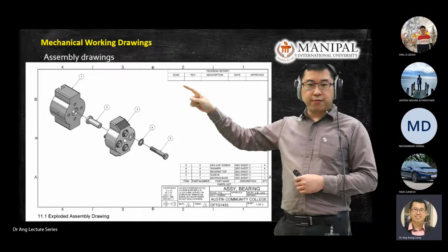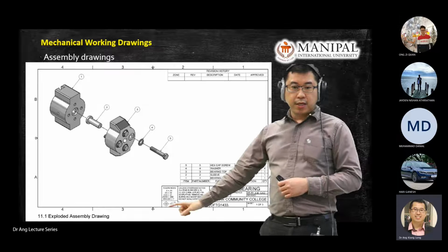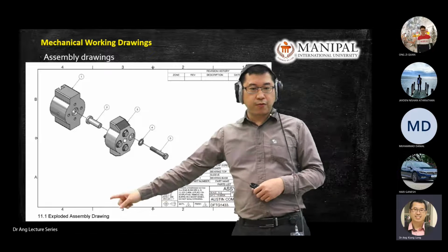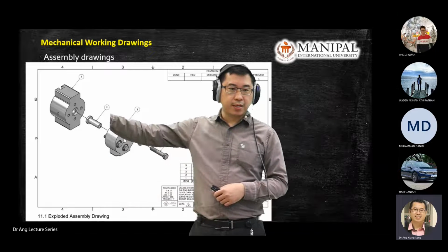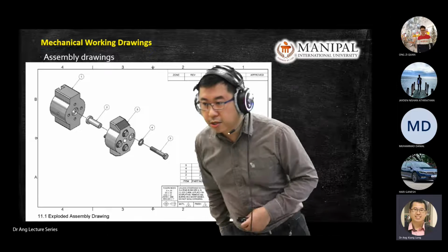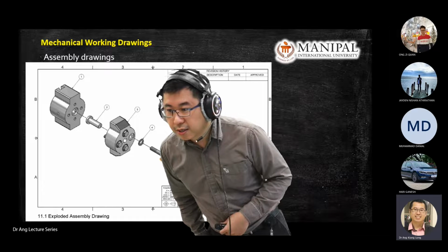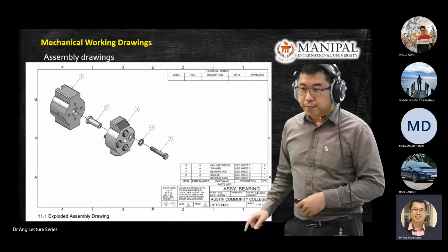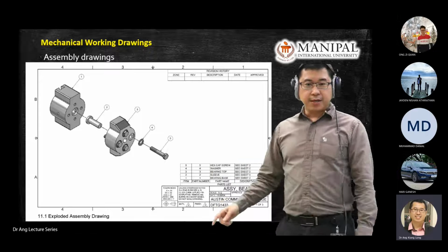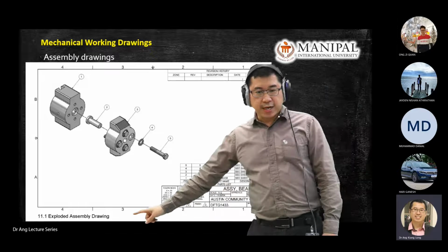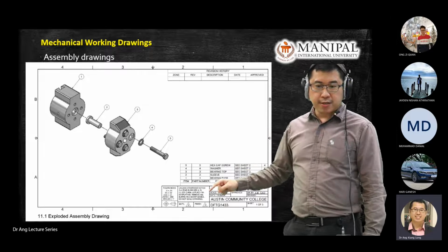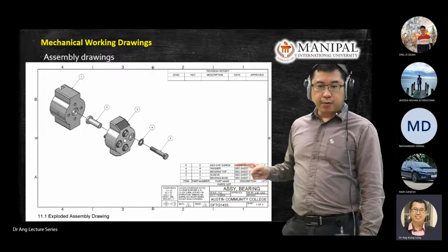We will expect you to give us the correct template, A4 size with regions 1, 2, 3, 4, and regions A, B, sometimes C. Okay, this is scale 1 to 2. I don't have the dimension here, but anyway, I will expect you to use the correct A4 template and the correct sizing, like I just mentioned, and then there will be a part list over here.